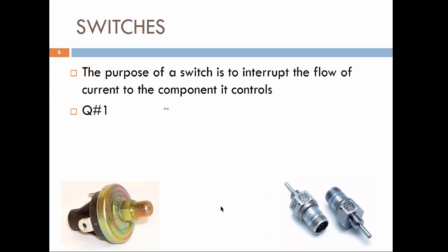So yeah, the Janitrol has a fuel pressure switch, so it can cut off the fuel. Tire pressure, that's coming out nowadays, and you want to monitor it, but would you need a switch for tire pressure? Probably not. And hydraulic pressure, yeah, you probably would want a switch, if the pressure got too high, to stop it from damaging the system.